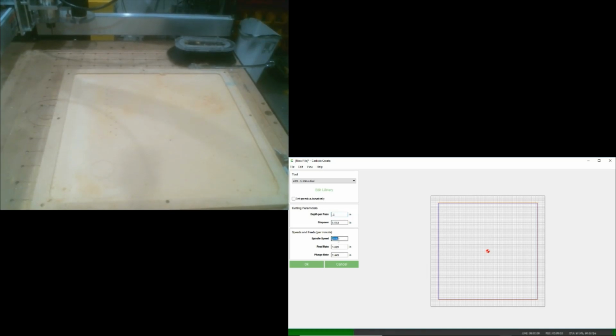Spindle speed. See, this is what I'm talking about. It set this automatically to 2445. That's 2,445 RPMs. No router even goes that slow. My spindle that I have, I can't even run that slow. That's for a true milling machine. So I'm going to go with 18,000 today, because if you're here with a DeWalt, that's as slow as you go. That's what setting number 1 gets you, is 18,000 RPMs.